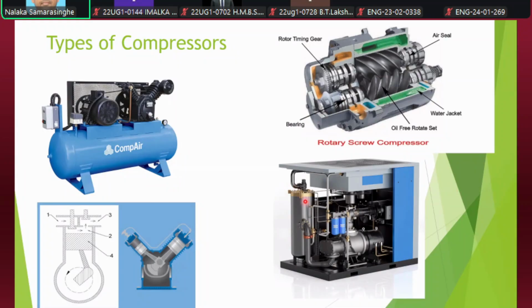Even though you use oil for the operation, the oil will be separated before the discharge of compressed air out of the compressor. So there is an oil separation circuit to run oil inside the compression circuit. We have a filter unit to filter out oil, and any contaminants in the oil will be filtered by the filters.